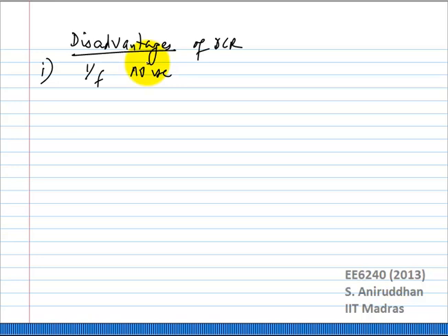Okay. Not will matter. It could matter. But definitely 1 over F noise of the baseband circuit is what will definitely limit your performance. So, you will need to have very large baseband devices. Okay. Now, this means that you need to have very large devices in the baseband. Okay. Anything else?